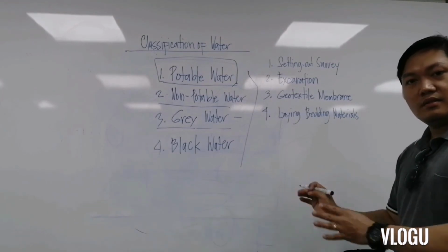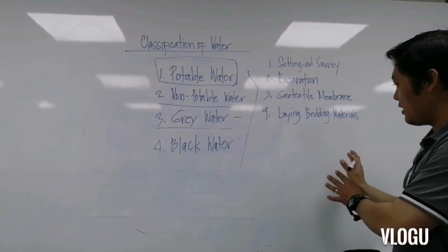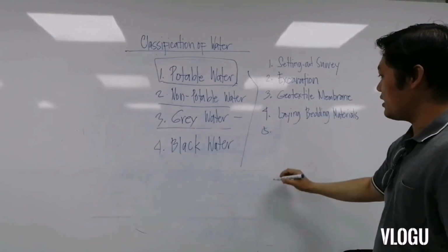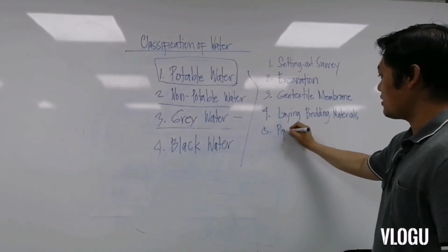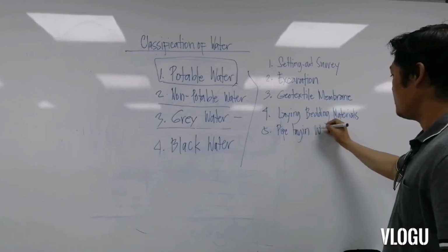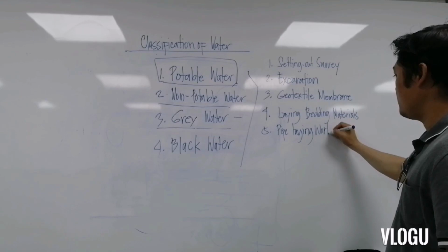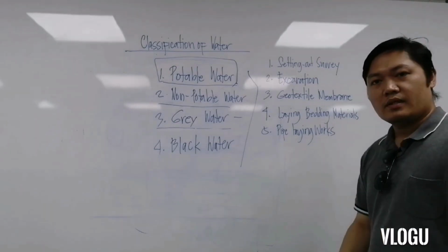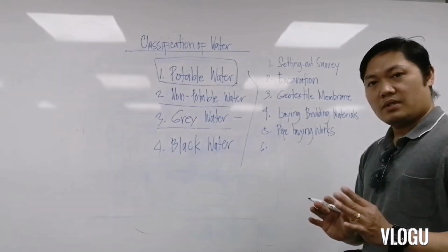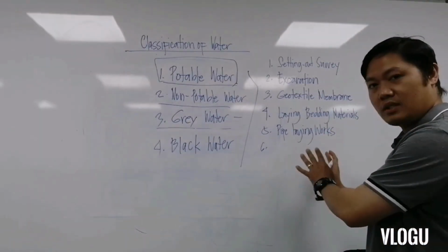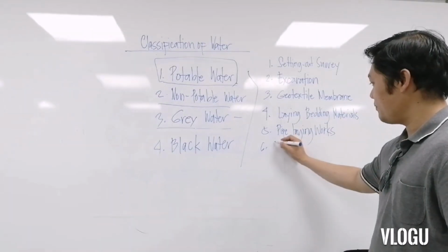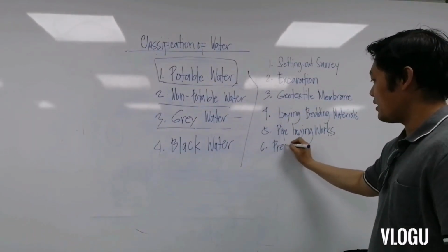Once you have completed the laying of bedding materials, you can establish the pipe laying works. After the pipe laying works, you can proceed with pressure testing.